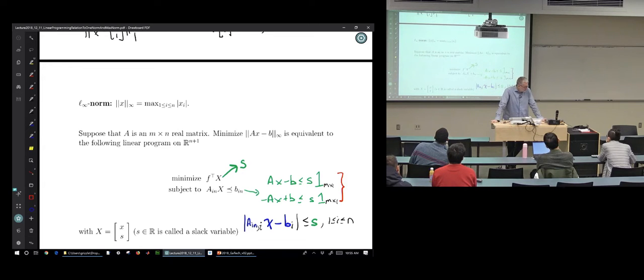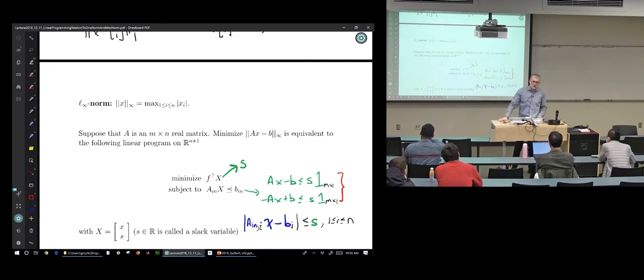And so the first problem that they gave me that was super hard was a V6 engine. They were trying to do air-fuel ratio control, and they were just making the transition from carburetors to fuel injectors. So a carburetor, remember what that was? You have air coming in, and then you have this little needle valve that mixes fuel, and so the air and the fuel gets mixed in the intake manifold before it goes into the cylinders, okay?